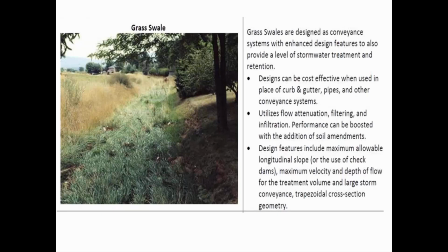Also, there's the advantage that the grass is going to keep the sediment in place. And so scour and erosion is a real problem in streams. If you can get grass to grow because you've got enough sun, in a lot of places here this wouldn't work because you've got a tree canopy over the ditch, and so there's just not enough sunlight for the grass to grow. But there are spots where it will, and where it does, it helps to prevent the channel from being damaged during big peak storms.